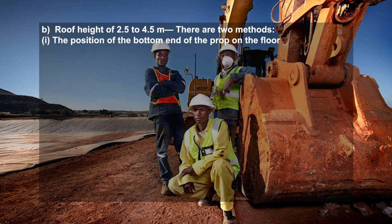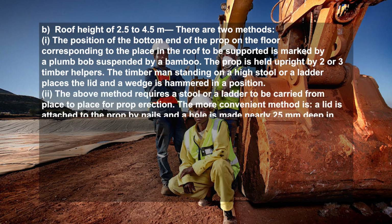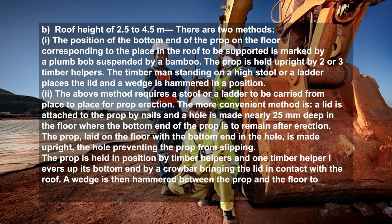The position of the bottom end of the prop on the floor corresponding to the place in the roof to be supported is marked by a plumb bob suspended by a bamboo. The prop is held upright by 2 or 3 timber helpers. The timberman, standing on a high stool or a ladder, places the lid and a wedge is hammered in position. The above method requires a stool or a ladder to be carried from place to place for prop erection.